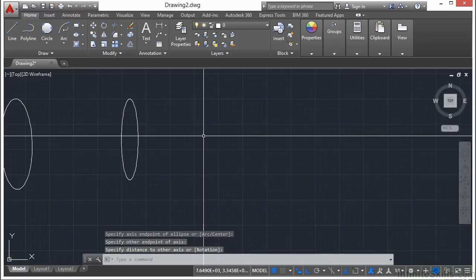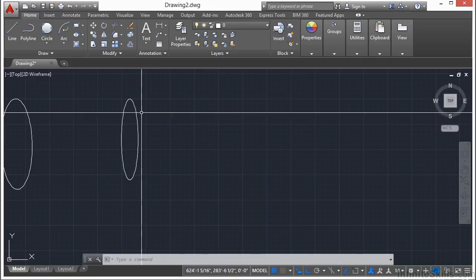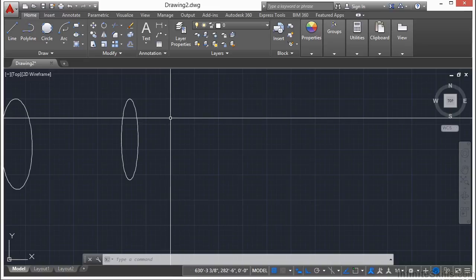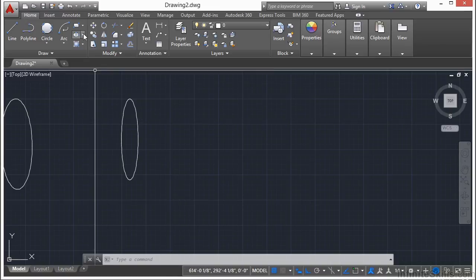And that's great. You can use this a lot of times if you're making piping drawings in a profile view with an exaggerated Y-axis. In civil design, you do this often, and so I get to do this quite a bit. So I'm drawing pipe cross sections like this all the time. So that's one practical use of an ellipse.